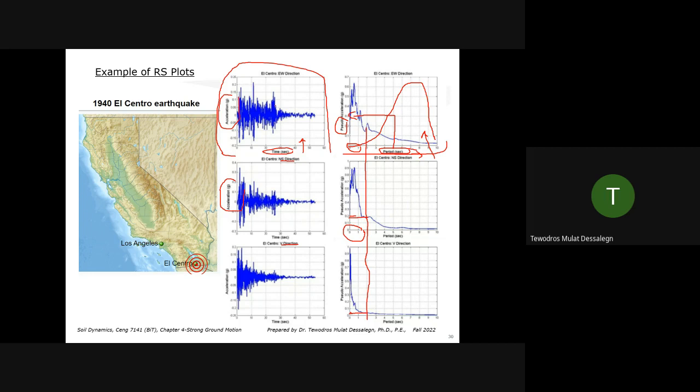But the time history goes by time. Let's say you are using a delta t of 0.0001, then this takes a lot of time to solve. So people choose a response spectrum analysis. It gives you a fast solution compared to a time history solution.